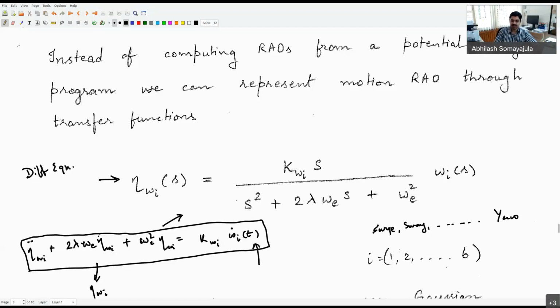Okay, what can I tune here? I'm actually tuning this value of k w. That is what I'm tuning. I can tune my k w so that my transfer function gives an output which looks similar to what I would get from a typical ship response. It won't exactly match, but it's a start. Notice that omega e here represents the encounter wave frequency. So depending on which wave I am getting, I look at that encounter wave frequency, and for that I compute the so-called response.